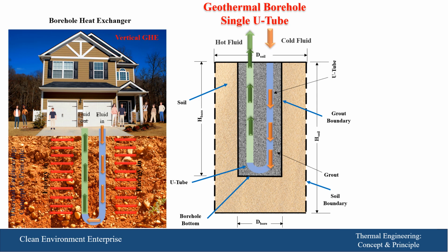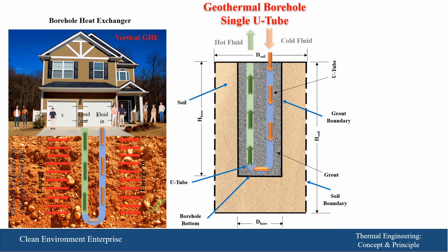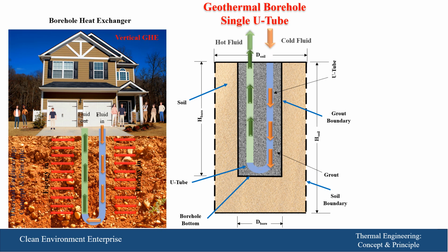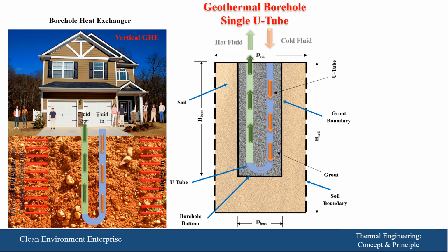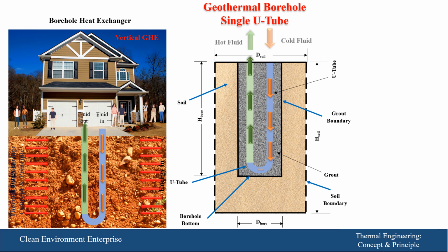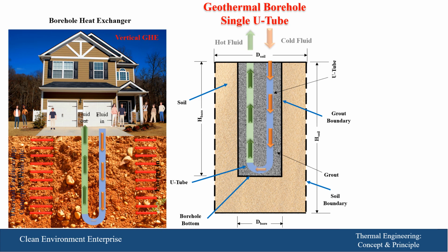It is composed of a U-tube, and the U-tube is installed inside a bore surrounded by grout material, and this grout material should be conductive material to facilitate heat transfer and conduction between the soil, the external part as shown in this figure, and the tube itself.